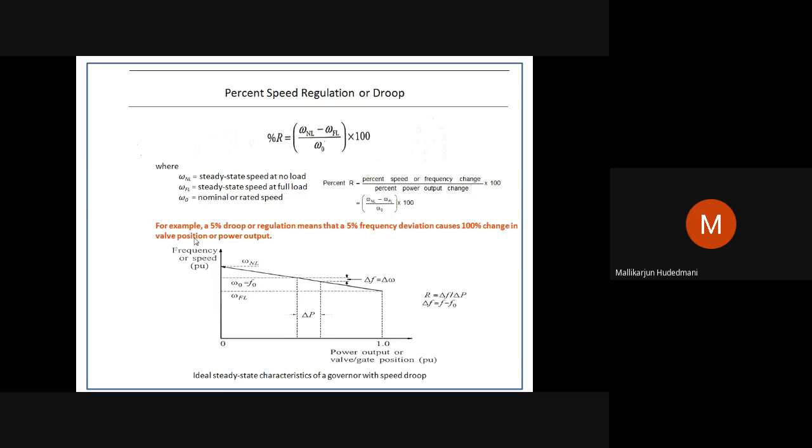At that scheduled frequency, what is the output that the generator is developing? That is understood from this curve. Where the generator's curve intersects the frequency, it gives you the point showing the output. Let us imagine this is 0 output, this is 50% output, this is 100% output. The entire length is divided such that the midpoint is my operating frequency. 50 Hz corresponds to 50% of the generator capacity. So this generator is showing an output of 50% of its capacity at base frequency.